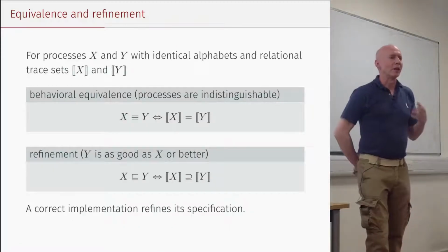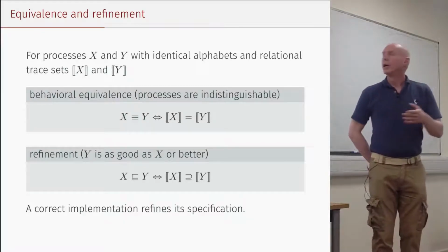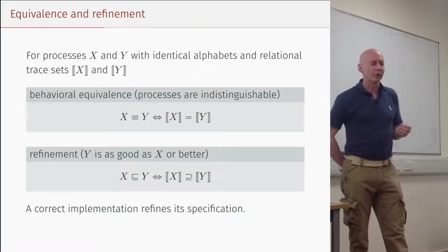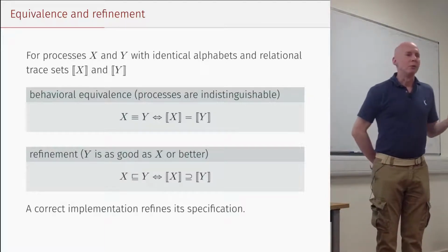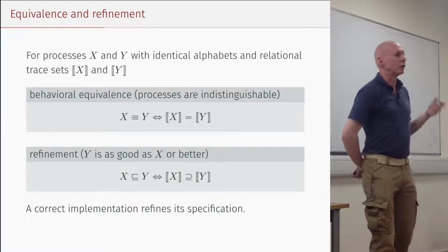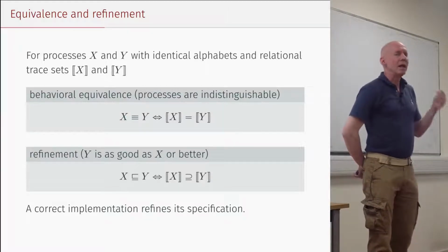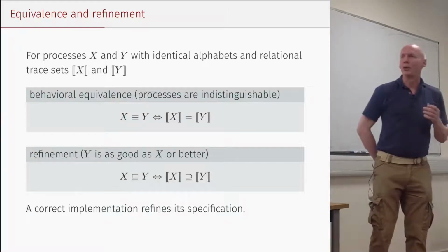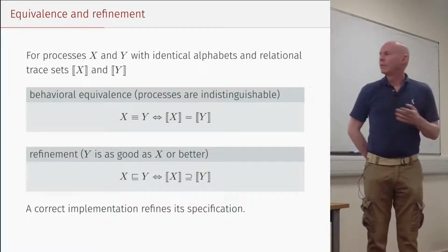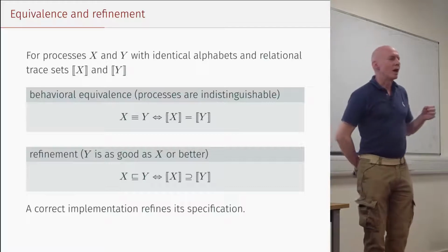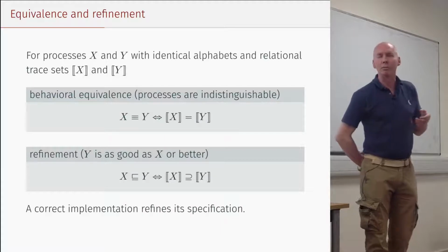As you may know, comparing languages specified by finite automata is a solved problem. That means you can take two completely different looking circuits and test algorithmically whether they are behaviorally equivalent. Maybe even more amazingly, if someone claims to have improved a circuit by adding desirable features to it without breaking backward compatibility, even a claim like that can be made perfectly precise and tested algorithmically. If it holds, then we say there is a refinement relationship between the two circuits. And refinement is the same relationship that we want between a specification and its implementation.